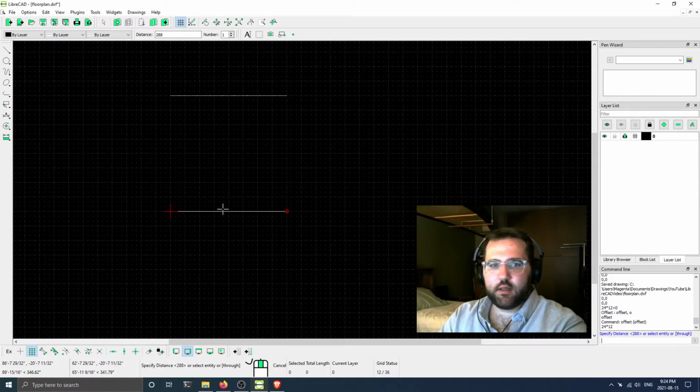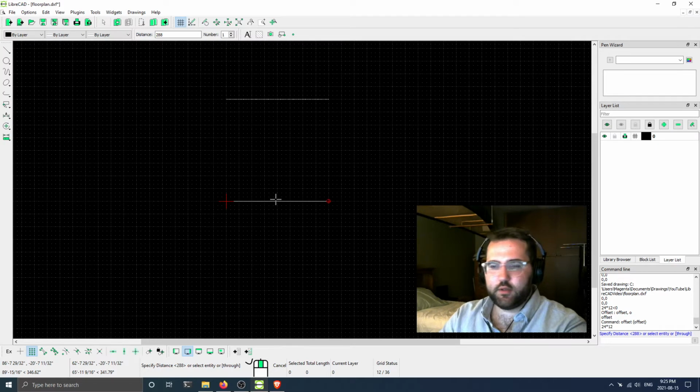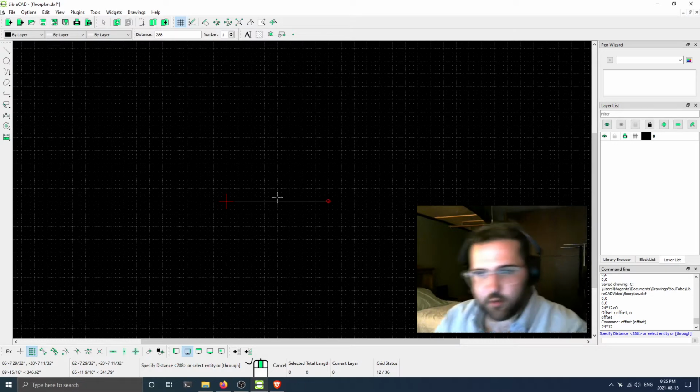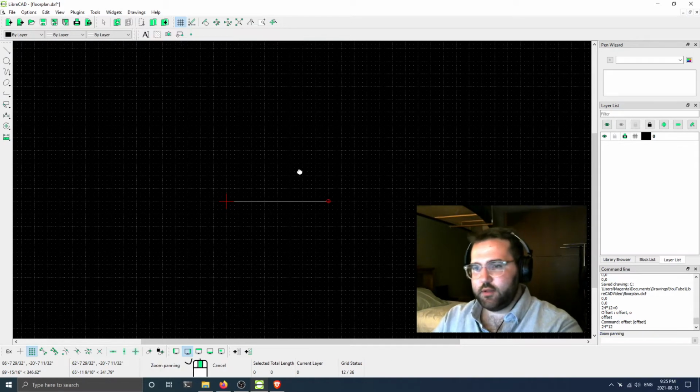And you can see that there is something to note about the offset side. So the cursor selects the object to offset, and it selects the direction to offset it by where it is relative to the line. So actually that doesn't help at all because the cursor doesn't resize when you zoom. But because the cursor is just off of the top side of the line, it's offsetting the line in this direction. So I'm going to draw upwards, so to speak, here.